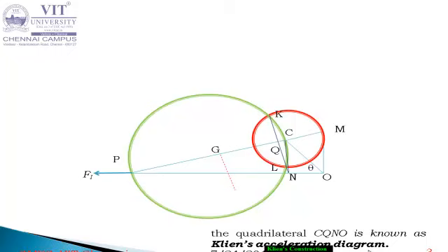Otherwise, how can you find it out? Other than this, by considering the connecting rod as a compound pendulum. From the compound pendulum formula, you find the time period. If you know the time period for oscillations, you can substitute and calculate the K value.